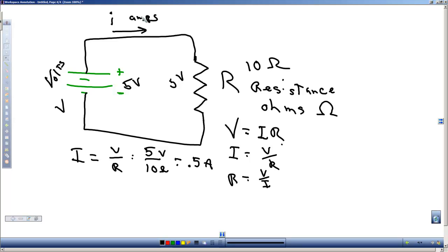So in order to calculate or figure the voltage, current, and resistance, those are the 3 key things we need. If we have any 2, we can figure the third. So definitely remember, and you definitely will need to know, the voltage equals current times resistance and all of the different iterations of that. The other equation that we need is sometimes the power equation.